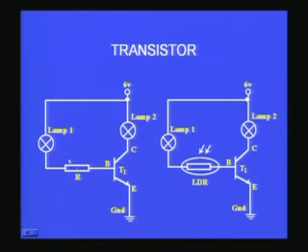If I remove this resistor by disconnecting the circuit, you would find this lamp also goes off, because to make this transistor work you have to have forward biasing of the base-emitter junction. Therefore you have to connect a lamp or a resistor or whatever with a power supply to make a finite voltage appear across the base-emitter junction, corresponding to about 0.65 volts or so. Only then will this lamp glow.